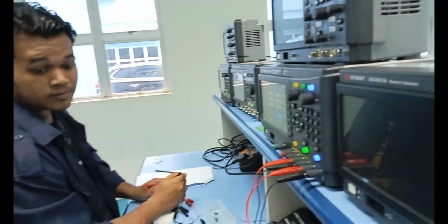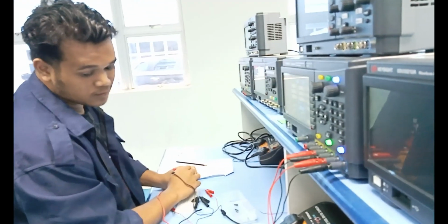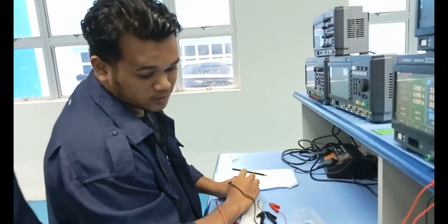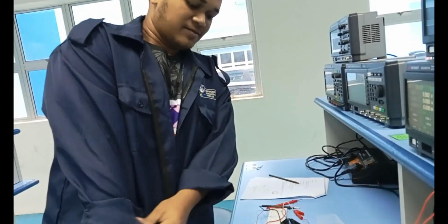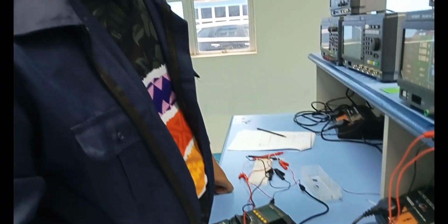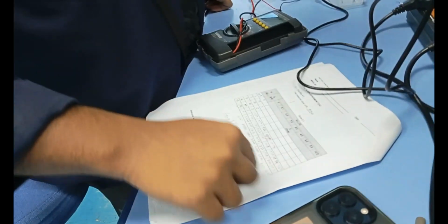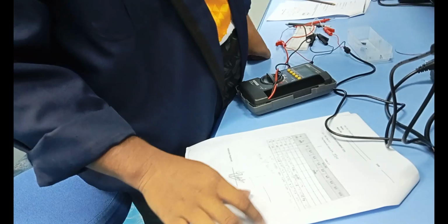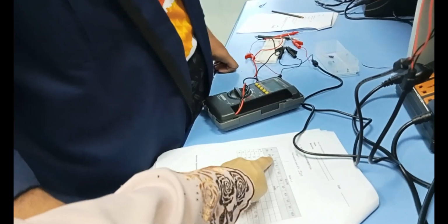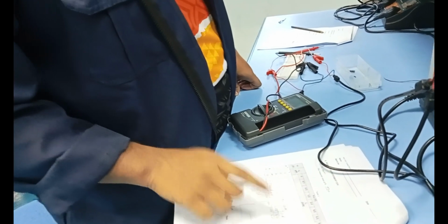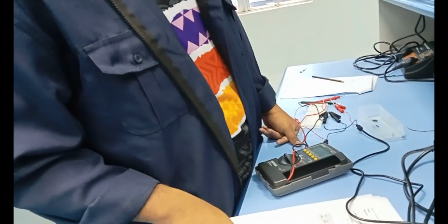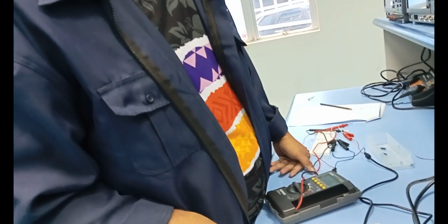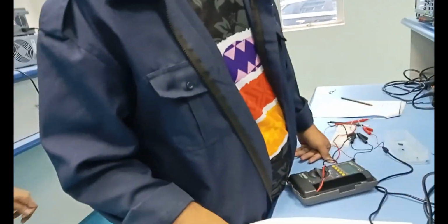Good. Okay, then you answer me. So what is the function of BJT? The BJT is for us to control, control what? It can function like what? When current IB increases, so IC will increase. When it increases up to a certain value, what will it do? It will saturate. Right. So it can function like a switch, or become an amplifier, to control the current. Okay, good.